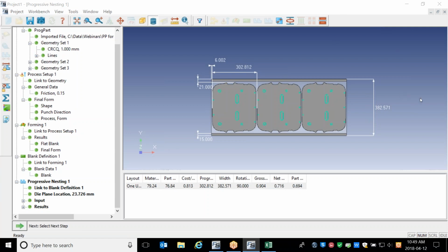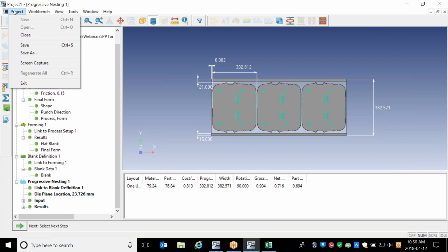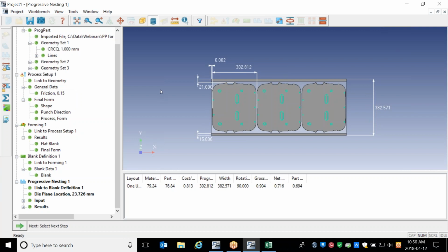Question regarding the export. You said the process plan that you have, you can export the IGES or the DXF. Not the process plan. You're only going to the nest layout. This layout that you see on the screen can be exported. We can't export the process plan at this point. You can or cannot? Cannot. Cannot, okay. And the export is only going to be the surface only. It's not extruding it out to create an actual sheet thickness. Correct.